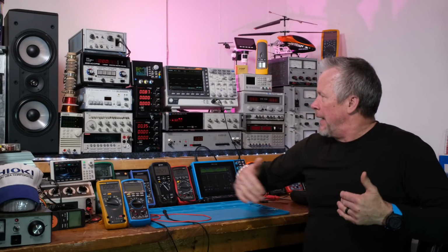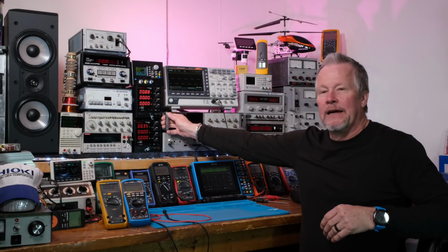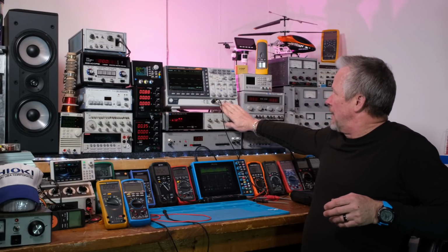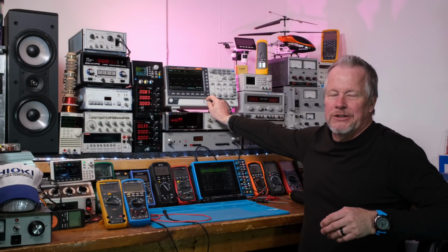So you have a little bit of leakage current on the metal. It actually hopefully goes down to the green wire and just travels back that way. But that's leakage current. So if you were missing a ground wire in one of your pieces of equipment, let's say you're floating a scope. Some people float a scope, and the reason they do that is all these terminals and everything, all this metal, except for the 2-volt calibration or compensation pin, and that's because it's real low voltage, but all this other metal is all tied to, like they show here, chassis. It's tied to chassis, which is earth ground.